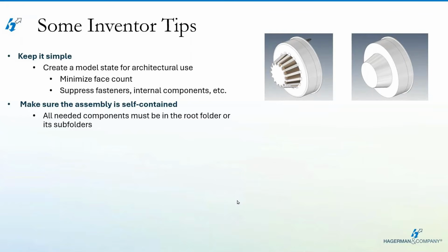Any other type of common folders you might have set up for your normal Inventor project file, you need to bring them down local, and you will make a local project file just for that one family. Okay, next.